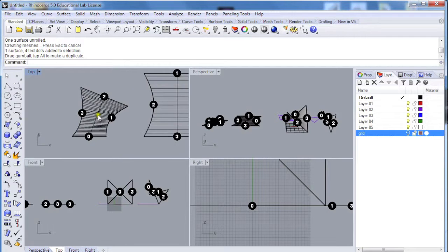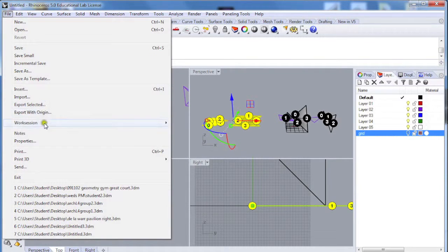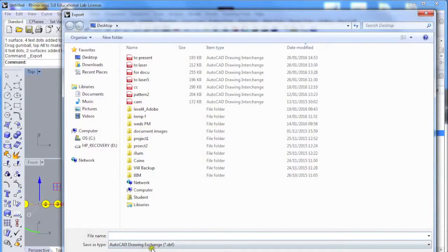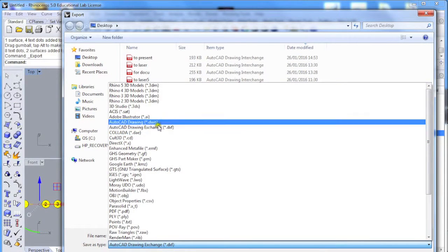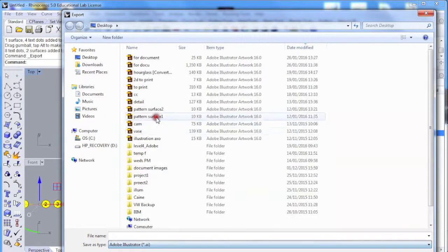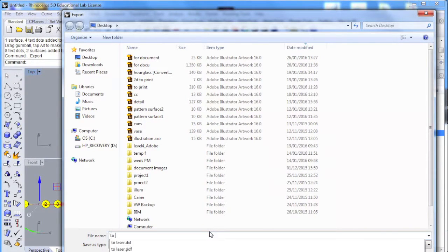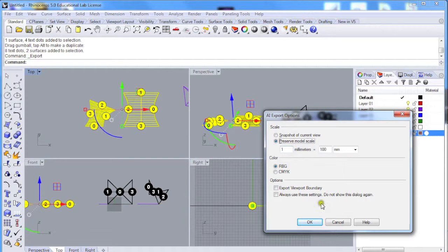And you can see it gives its correlating numbers. So if you laser cut that on a piece of fabric and then stretched it out into a grid at the same positions, so I'm going to save this as an Illustrator file. So there's those two settings. If Illustrator doesn't work, use DXF.